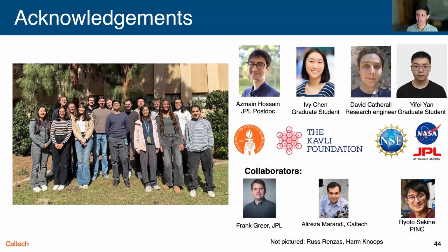Fundamentally, point source methods have a challenge compared to sputtering, where you can do 12 inches very easily, right? Having said that, there are ways you could certainly imagine that you could engineer your way out of that if you needed to. But I think certainly it's an easier case if you start with a lower volume industry where, despite it being a point source, you don't really care if the wafer flow is slow. In addition, in the quantum industry, nobody has a personal quantum computer right now, so it's not really an issue in terms of that nature of scaling. Absolutely.